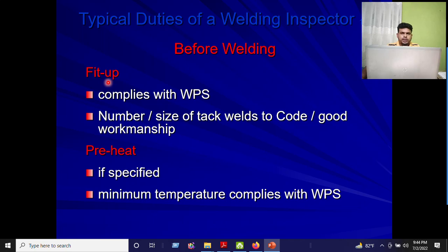Then we have to check the fit-up compliance with the WPS. So is the fit-up in compliance with the WPS or not? The number and size of tack welds should show good workmanship. So we also have to check whether the tack weld size and tack weld number are as per code or not. Preheat as specified: if the WPS mentions preheat, we have to check whether that specified preheat is maintained or not. The minimum temperature should comply with the WPS. As per the WPS, whatever the minimum temperature is, we should comply with it.